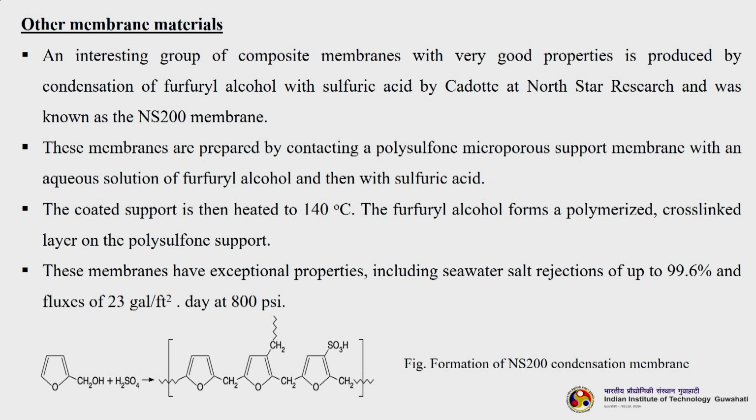So, among other membrane materials, an interesting group of composite membranes with very good properties is produced by condensation of furfuryl alcohol with sulfuric acid by Cadotte at North Star Research and was known as the NS200 membrane, the trade name. These membranes are prepared by contacting a polysulfone microporous support with an aqueous solution of furfuryl alcohol and then with sulfuric acid. The coated support is then heated to 140 degrees centigrade. The furfuryl alcohol forms a polymerized cross-linked layer on the polysulfone support.